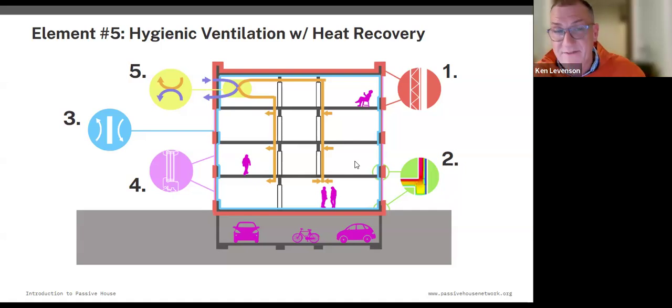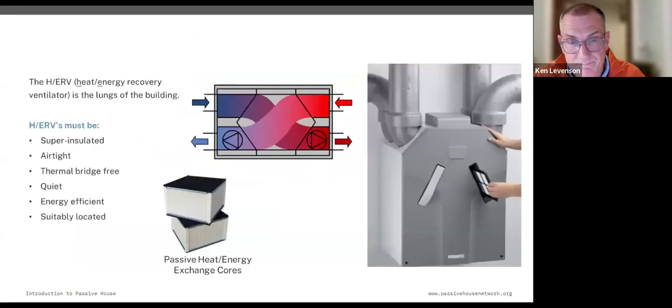Because it's running 24/7, we want it at a relatively low volume. This is not air conditioning-like blowing. We also want it to run quiet, and we don't want to lose that much energy, right? So it has a high efficiency heat recovery, and we can recover now over 90% of the heat that's being expelled and bring it back into the incoming air. So that helps keep the interior hot in the winter and cool in the summer. It can also do some humidity recovery too, if that is needed.